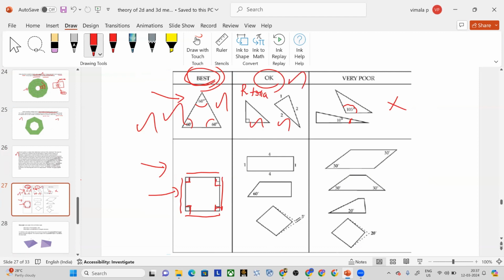But this is also okay, which means if you are getting a triangle, that is also fine. Or if one side of the triangle is alone getting some 60-degree angle, or if you have some distorted square or triangle having a very lesser value of, let's say, 5-degree, that is also okay. But you should not get something like a trapezium or parallelogram. That is not at all acceptable. This is considered as poor mesh. Or a distorted square or rectangle having more than 5-degree, that is also not acceptable. So these kind of meshes should be avoided. Okay.